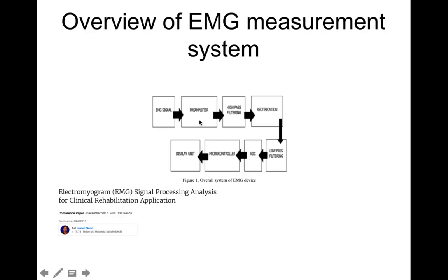So a lot of these signals come in very small, microvolt to millivolt range. And so a lot of times you will want to use just a simple inverting or non-inverting amplifier as a stage right at the transducer so that you are not as sensitive to noise and you have a better signal to noise ratio if you have, say, a noisy lab environment.